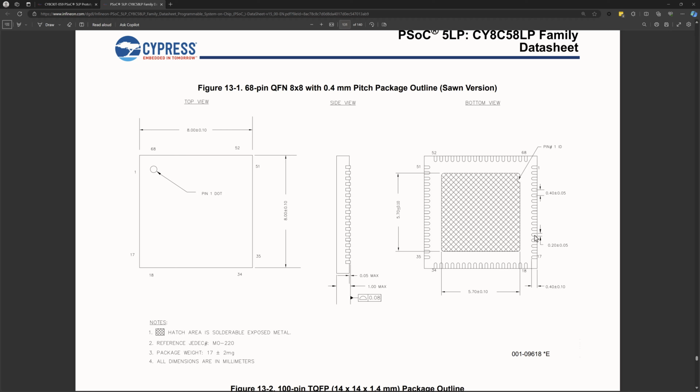So that means I either need to come out with a smaller trace and then switch it over to a wider trace, or run all the traces from this to where they connect with 0.2 millimeter, and then everything else on the board goes to 0.254.